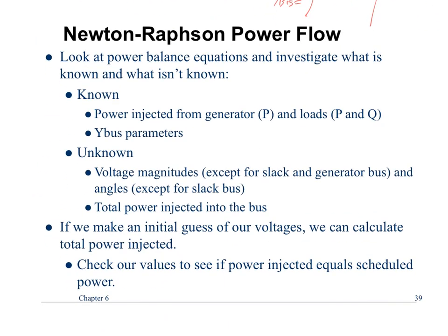They do belong in the Y-bus matrix, so that way you know which is the real part and which is the imaginary part. But in your power injection equations, you've got to take the J term out of there and just make sure that that's a placeholder to show where the real part and where the imaginary part is. Okay?